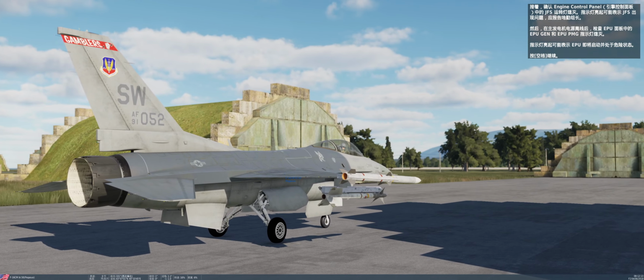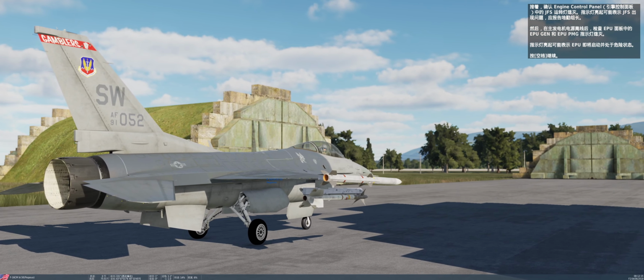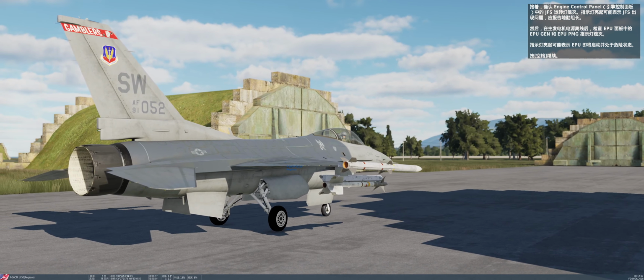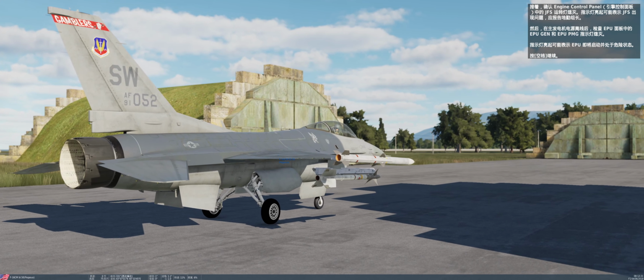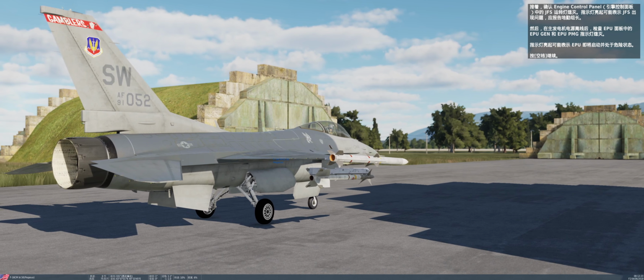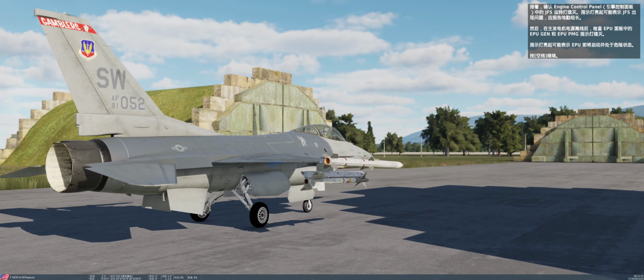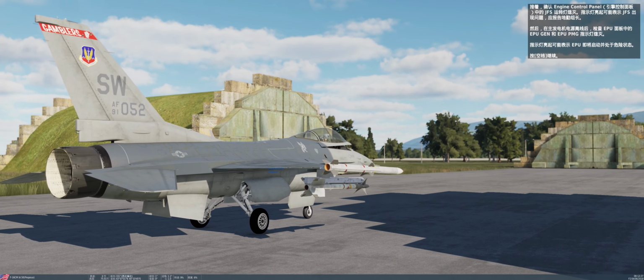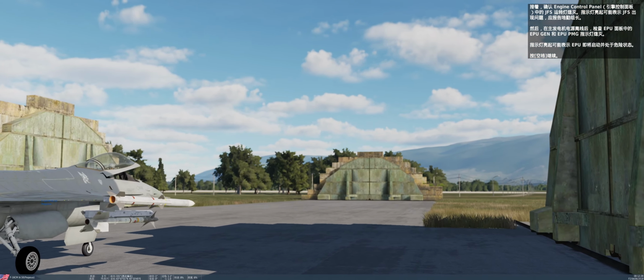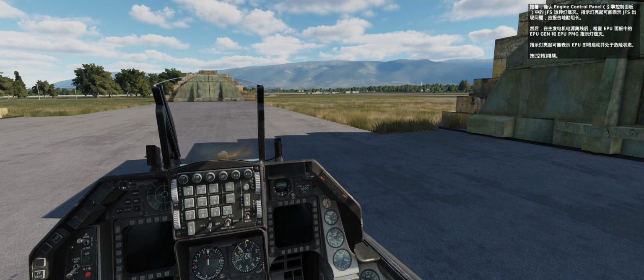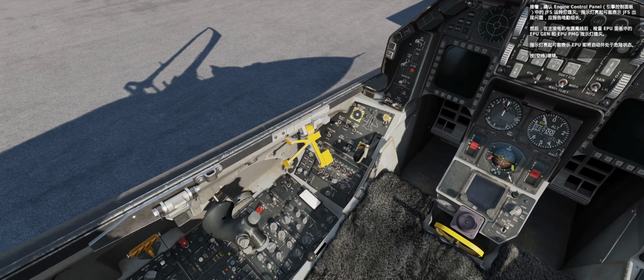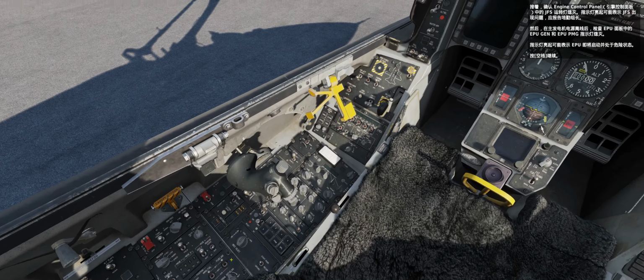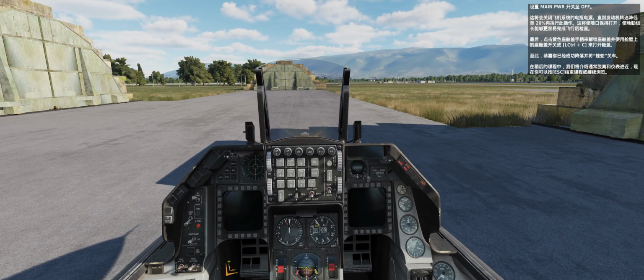Next, confirm the JFS run light is off on the engine control panel. The light could indicate a problem with JFS that should be reported to the crew chief. Then, after the main generator power drops offline, check the EPU Gen and EPU PMG lights are off on the EPU panel. The lights on may indicate an impending activation of the EPU and a hazardous condition. Press spacebar to continue.